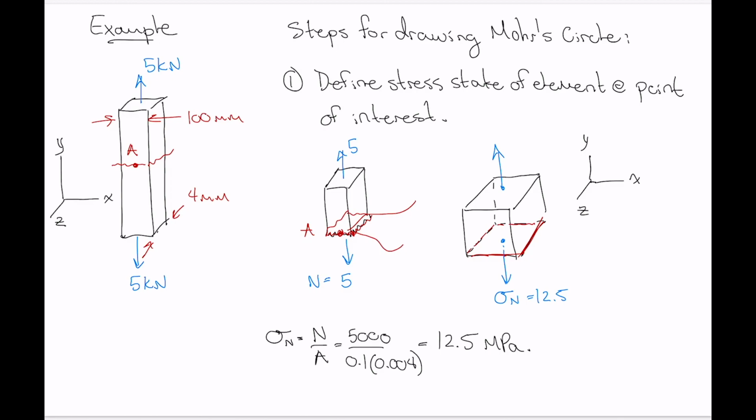Now our normal stress, sigma subscript n here, is our only stress, so there are no stresses to combine. So this would be more appropriately labeled as the stress in the y direction, sigma subscript y. Now, we're going to have stresses with y as a subscript since we're dealing with multiple directions, and we need to start getting careful about labeling the orientations of our stresses.